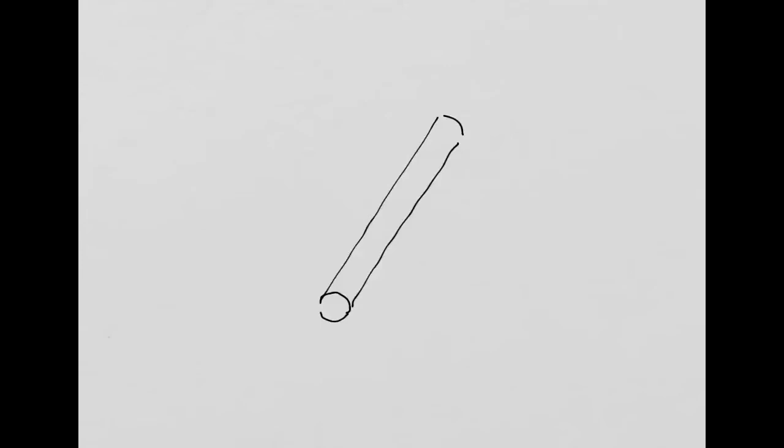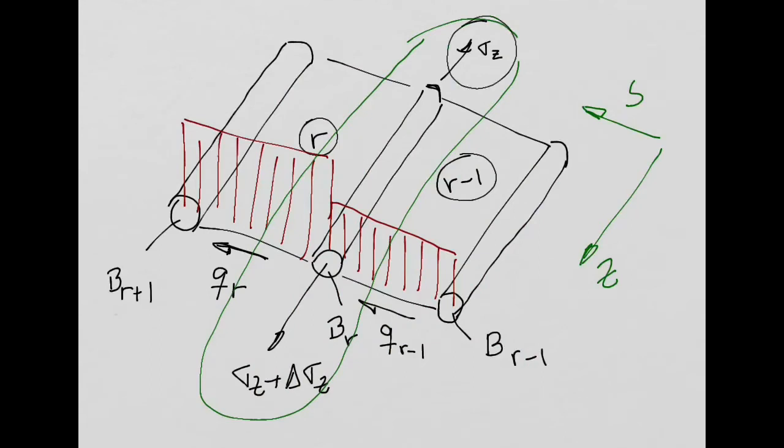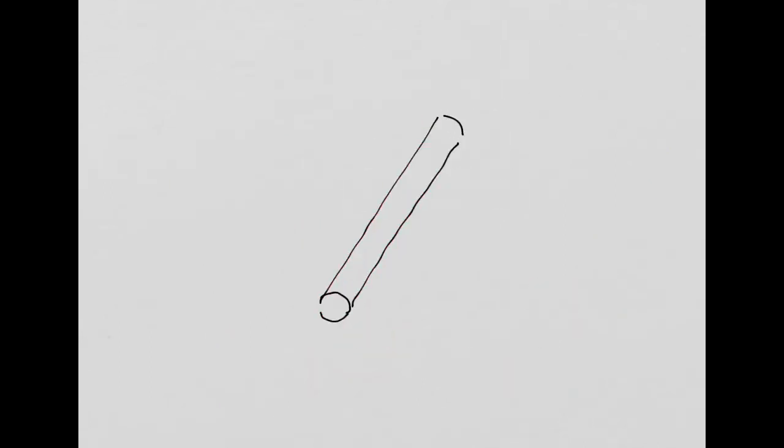First I have the direct stresses, right? If you look here, I have this sigma z and this sigma z plus delta sigma z. So I'm going to add these two first in my boom. Here I have sigma z, and here I will have sigma z plus delta sigma z. All right? So the direct stresses due to the bending, the booms, they carry those direct stresses. That's what I have. But now there is another thing that is connected to this boom,